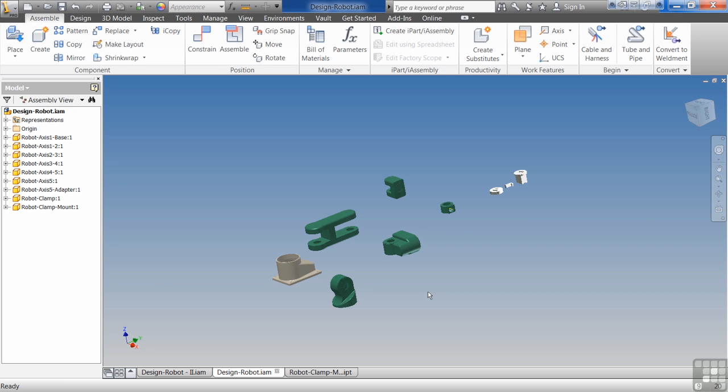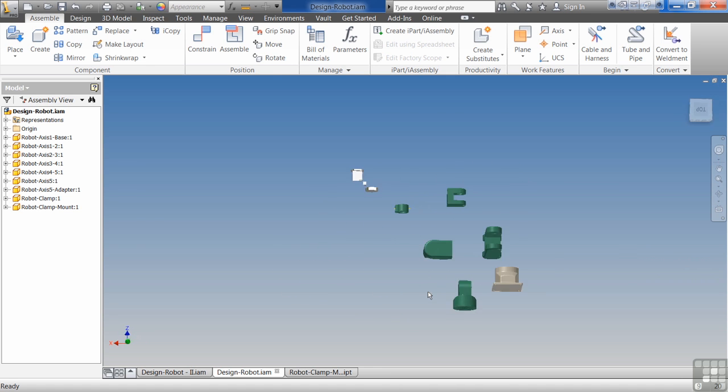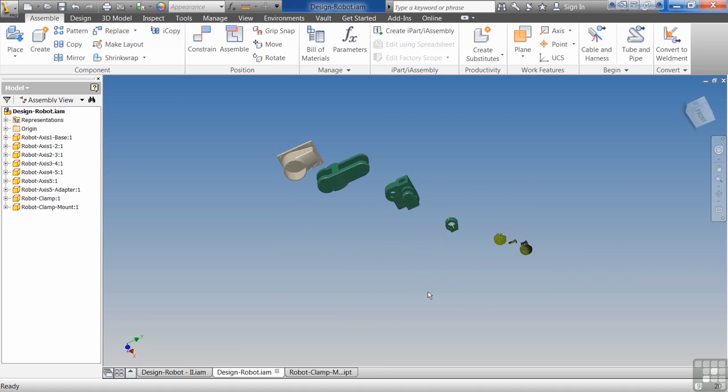So as we get into assemblies, it becomes more and more important to be able to move and look around things. So if you don't have a 3D controller, get used to the view cube and get used to the hotkeys and the shortcut keys for rotating around. The biggest thing I get on my students about is not rotating a part around. Don't try to do it all from one view. If you watch me work, you see I'm constantly looking at different views because I can't see in every direction.